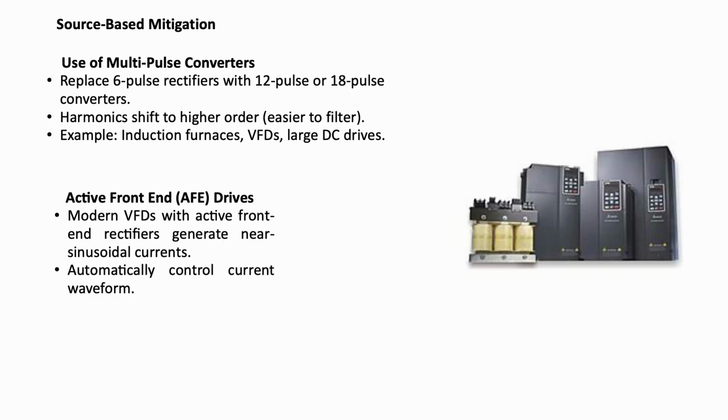This technique is common in large DC drives, induction furnaces and heavy industrial systems. So more pulses means a smoother waveform and lower harmonics. The next is active front end AFE drives. Modern variable frequency drives now come with active front end or AFE rectifiers.